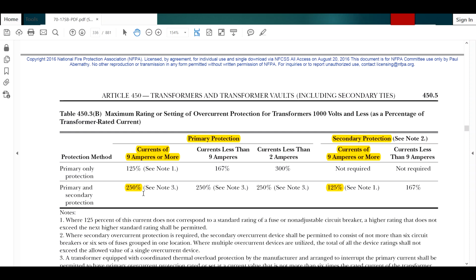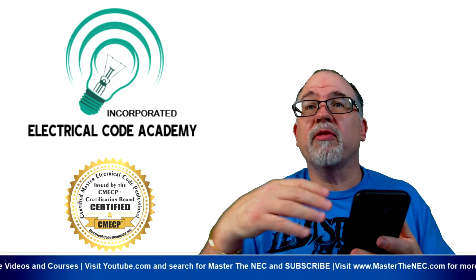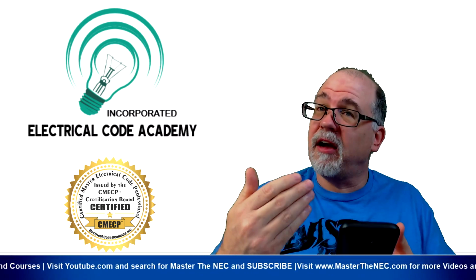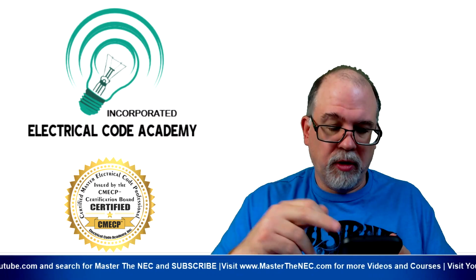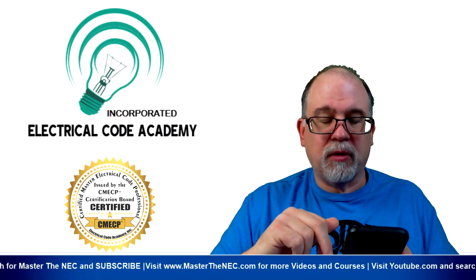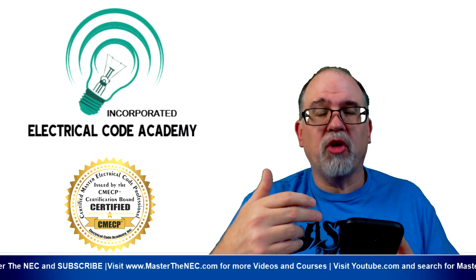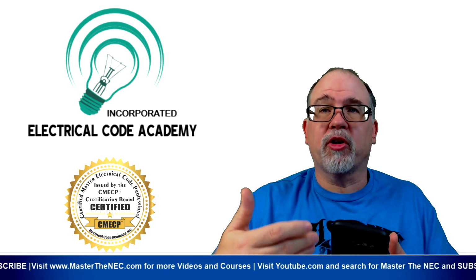So what is the maximum rated overcurrent protection device for a 1,000 volts or less transformer? What is the maximum? If you're doing a calculation on an exam, we see that it's 250%. So if you've got your calculator handy, you're going to actually do that calculation. We already calculated in part 1 of this series that the primary current rating was 90 amperes. So we did 90 times 250%, and that equals 225. And so 225 is the maximum primary overcurrent protection.